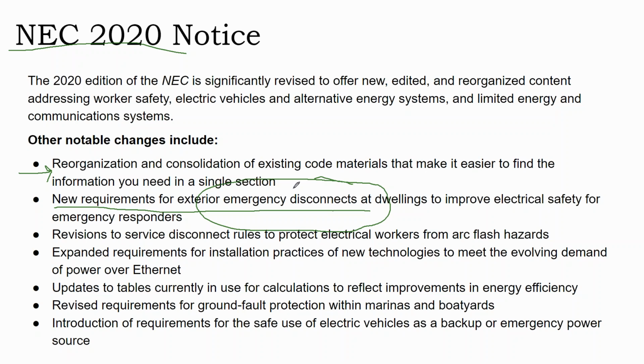But if you don't lock your exterior disconnect switches, they become safety hazards themselves. People can open them up, stick their hand in, and electrocute themselves. So that's the main safety concern about these emergency exterior disconnects, is to make sure that they are locked up at commissioning, or when the grid side is tied into the top of that disconnect.